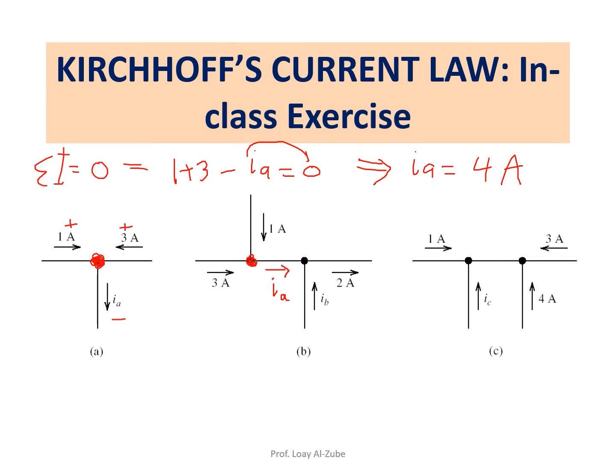Make sense? Guys, same thing goes for C, right? You have two currents getting into this point, but you need to have something coming out. I will call this, let's say, IA. And then you find it on the other node. And do not forget the unit, amperes. And guys, here's one more thing before we move on. See on my first example, I told you it's 4 amperes, but the arrow is saying it's going out. If I want to really use my notation, it should be negative 4. But as long as I don't want to put negative, I say that it's coming out, like this, because it should be coming out of that.